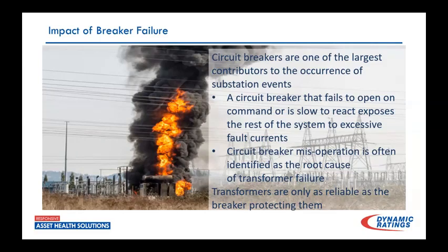So my takeaway was that not only is that putting a lot of strain and causing an increase in outage times, but there are effects on your transformers too. If you start going through and looking at the stations historically where we knew we had these slow operation problems, you would find those were also where you had transformer problems a lot of the time. So there's definitely a correlation between those, and we'll go over that.